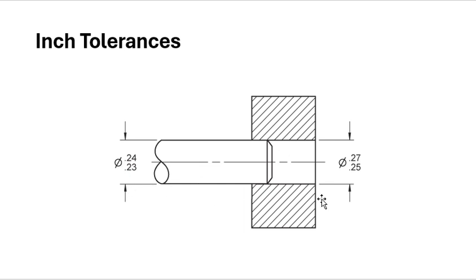But be very, very careful when you deal with the drawing if you want to keep your career in this line. It's because the common mistake that costs a lot of money in production, because you're doing mass production, is that little decimal right there. Okay, so 23 and 0.23 is a big difference. Trust me. Some of the engineers, some of the designers, some of the CAD drafting people, they miss it. People are all stressed out, and people get fired, of course, because of this little decimal. Okay, so even though we follow the inch tolerance with the British or English writing system, be very, very careful, and you will have to double check, triple check, quadruple check, check that little decimal. Okay, so I am pointing that out by taking about a minute, so you remember when you work on some projects.